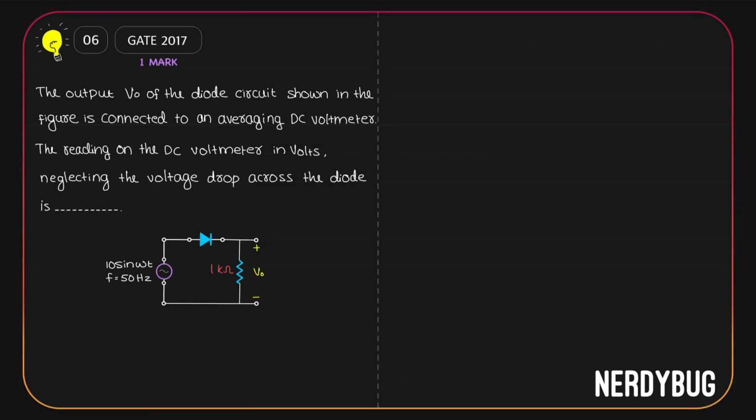This is also the simplest question once you recognize the circuit. What we have over here is simply a half-wave rectifier. So basically what we have to find out is the average value of the output of a half-wave rectifier, which we know is V0 by pi.